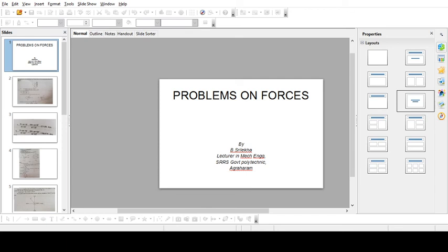Next, direction of the resultant. So tan theta is equal to sigma v by sigma h. Sigma v we got 0.866P by 0.49P. So both P's get cancelled. The leftover is 0.866 by 0.49. That will give you a value of 1.767. So theta equals tan inverse of 1.767, that is 60.49 degrees.